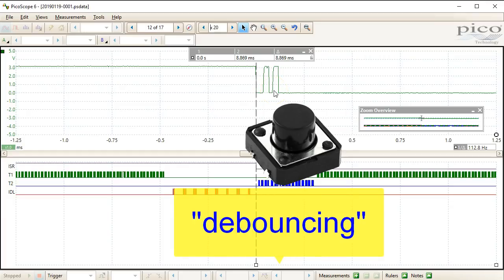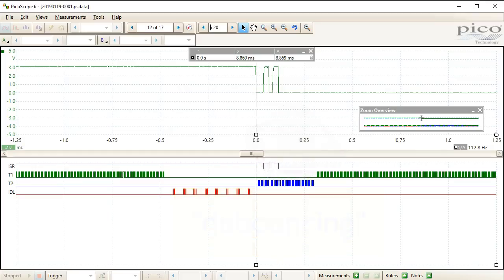Let me only mention here that you should definitely not release any production quality software with the current implementation, and instead you should properly debounce all your switches in software. However, for this lesson I chose exactly to use the noisy signal, because it provides more extreme stress tests for your semaphore, and in doing so it will allow you to gain a deeper understanding of how a semaphore works.